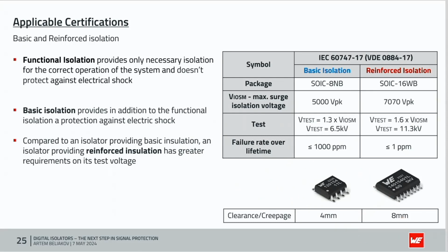Clearance and creepage distance for SOIC 16 wide body package, which provides reinforced isolation, is 2 times longer than for SOIC 8 narrow body package, which provides basic isolation.